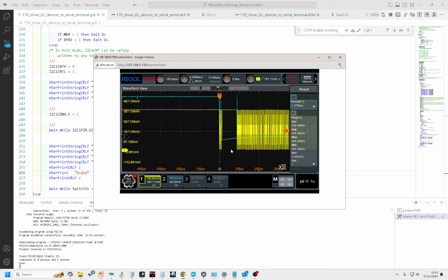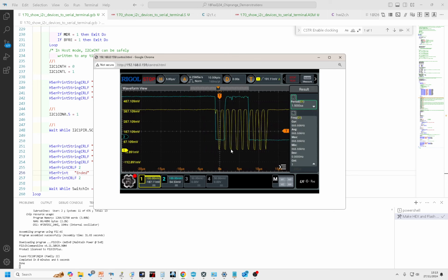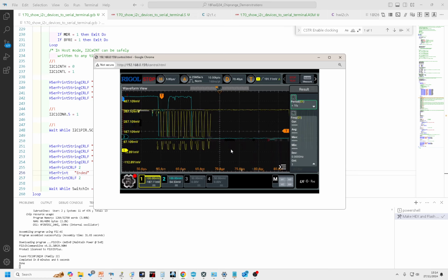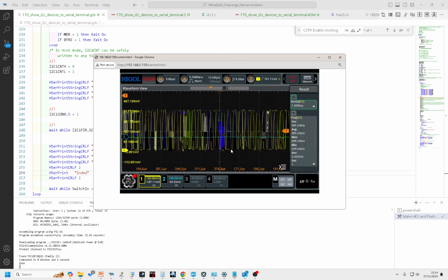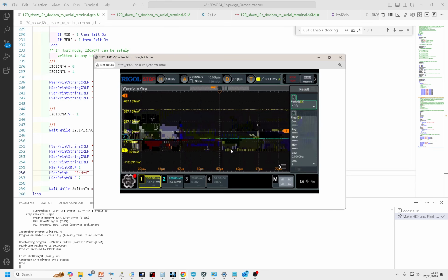Let's zoom in. Remember, what we're looking at is the shape of the 7/8, and you can see from high nibble, low nibble, that is definitely 7/8. But then if I move across, the stop signal comes in, and all I'm getting clocked out is zeros. Exactly the same as the protocol analyzer. They are the same thing. What's happening? I have no idea.